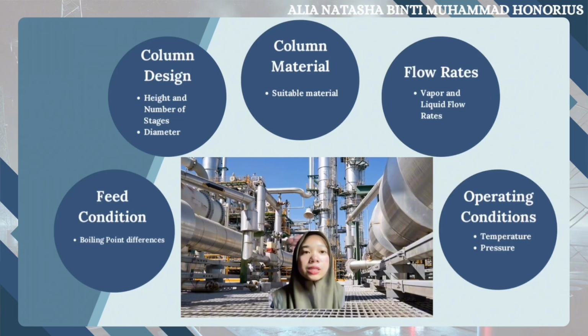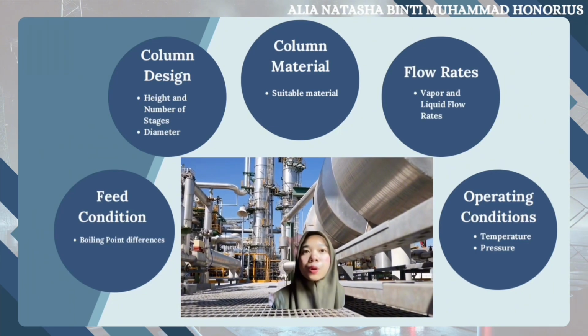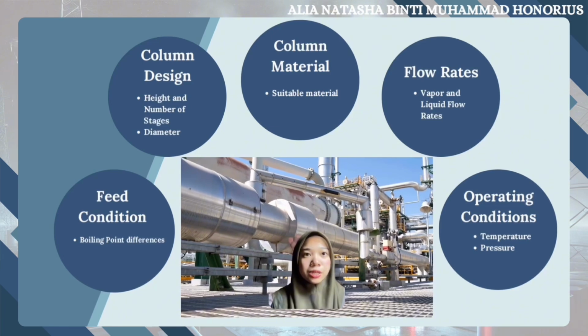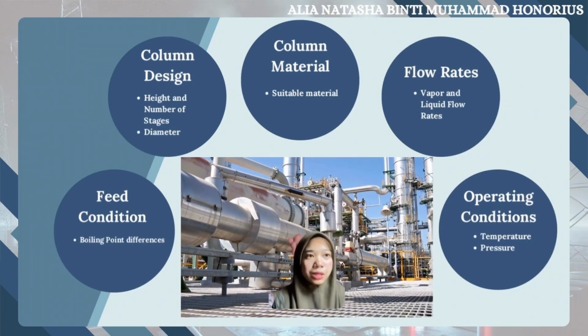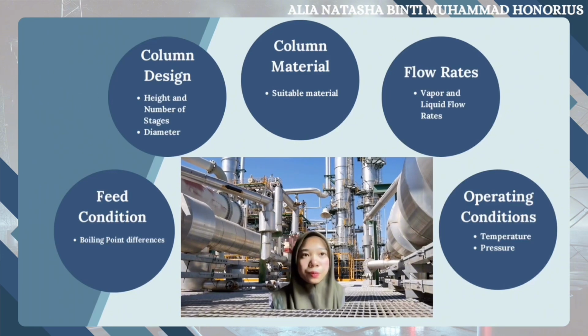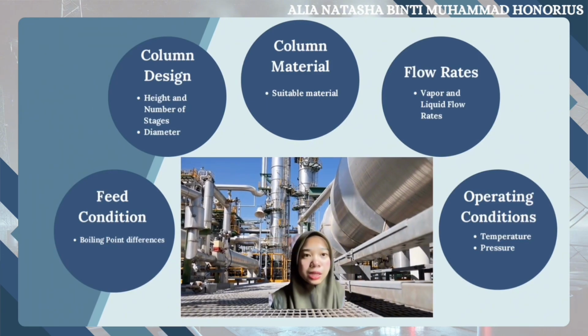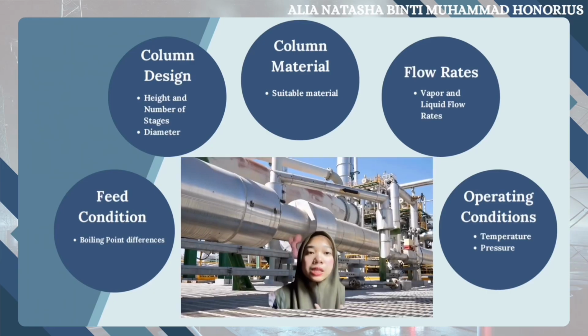And the last one is operating conditions, where we will talk about the temperature and also pressure. As for the temperature, an appropriate temperature must be maintained throughout the column to achieve the desired separation. And the pressure must be adjusted to optimize the separation process, especially for temperature-sensitive components.